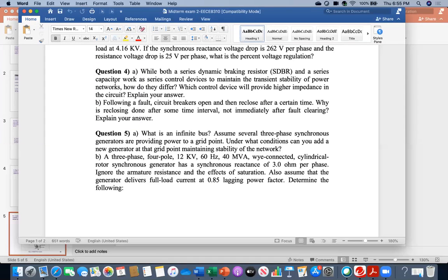On the other hand, in case of a capacitor, it is not doing anything with the resistor, but it is compensating the inductive effect. So consequently, the power factor is getting improved. So everybody, could you follow me? Does it make sense?